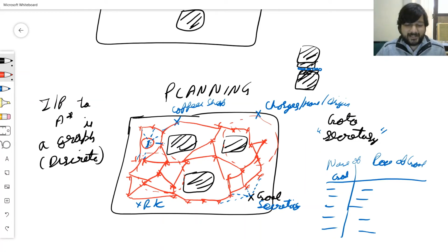So satellite navigation tries to guess where you are, connects you to the nearest exit. So that's exactly what I'm doing. I'm connecting the robot, which is not at a known position as per the red roadmap, to the nearest locations, which could be possible exits, and similarly the goal. And then I use my standard graph search algorithm in order to calculate the path. Which is this one.